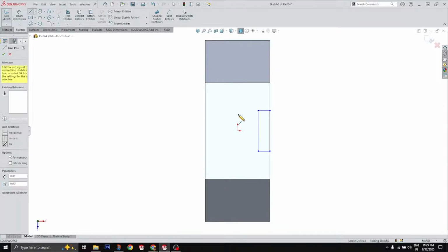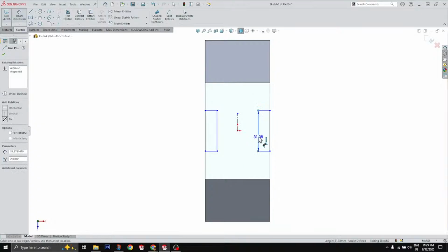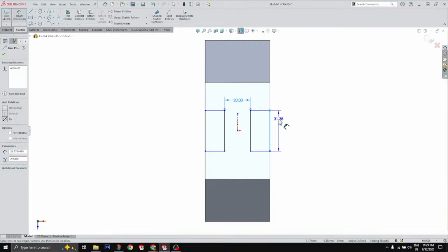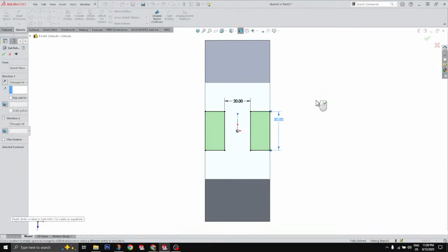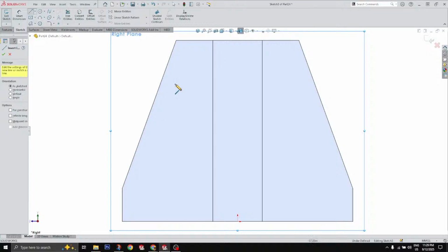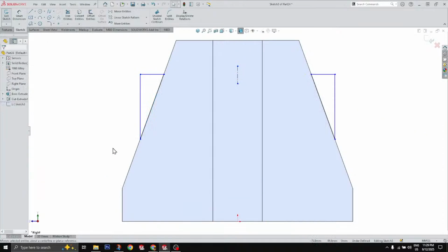On the right, we see Het Patel using Onshape, and it looks like he's modeling this thing up. He's decided to put the origin in the lower left corner there, and then he's just going to kind of model up this part with the dimensions that are on the print. And we're going to see if maybe he tries to use some symmetry on this part, or if he goes in and maybe uses some angle dimensions to lock this thing down. Looks like he's going to try and go with some symmetry. Look at that. Very nice to lock that all down.